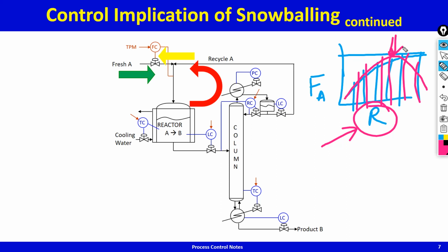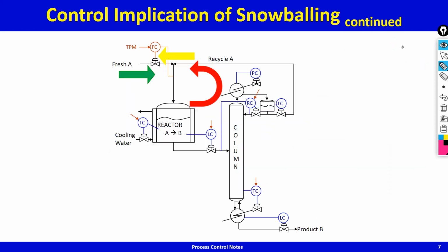Operator can adjust the set point and still operate at the maximum. Yeah. So in this case, you don't see large swings in the recycle rate because you're holding the recycle rate fixed, and therefore you're able to operate at the maximum or very close to the maximum. You're able to operate the process close to, for example, the flooding limit of the column.